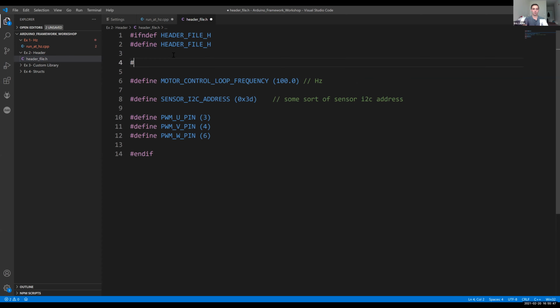It's basically a way for you to tell the compiler, whether that's Arduino or VS Code, whatever you're using, you can say, I want to do like BALL_LAUNCH_DELAY. Also, just a side note, I use all caps for the defines because they're not actually variables, but they look like them in your code. So I just use all caps to differentiate what is a variable and what is one of these predefined values.